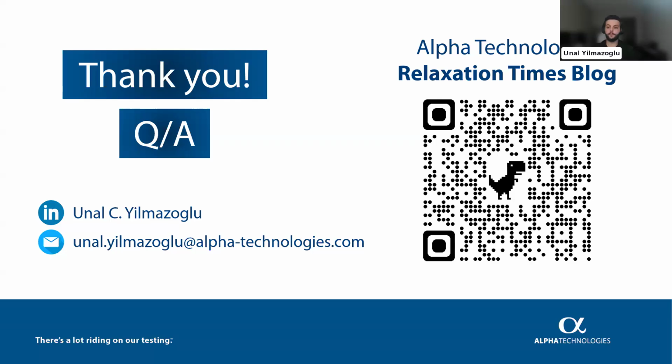Thank you. Perfect question. In the crossover point determination, I use 7% strain at 100 degrees C. Especially when it comes to TTS, I would suggest the temperature window should be at least plus or minus 10 degrees C, and I would run perhaps 5 different temperatures to get a much more reliable master curve.